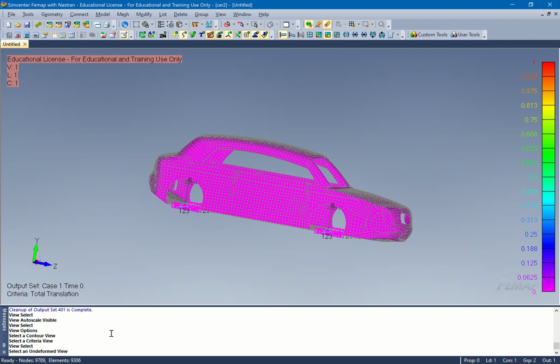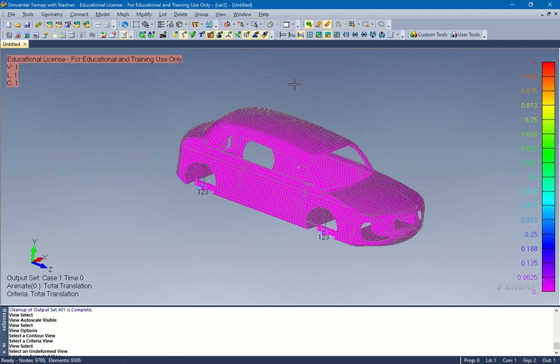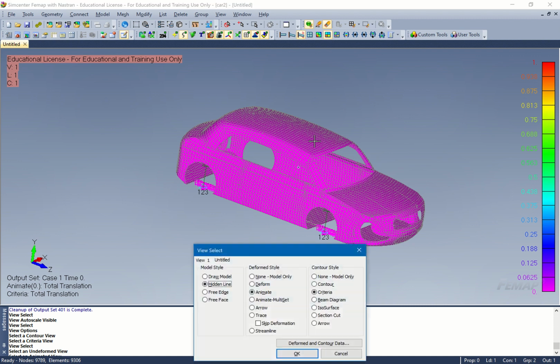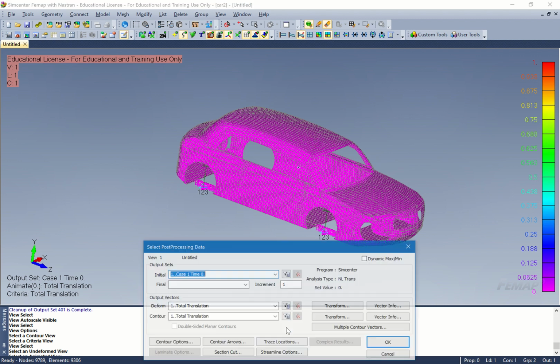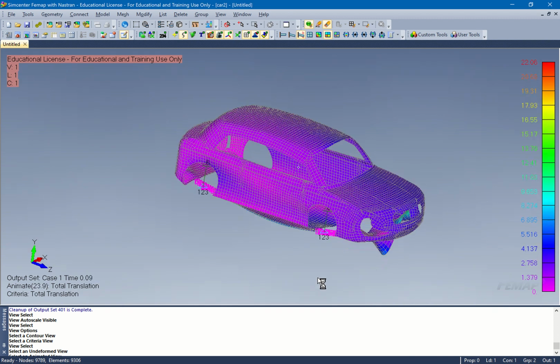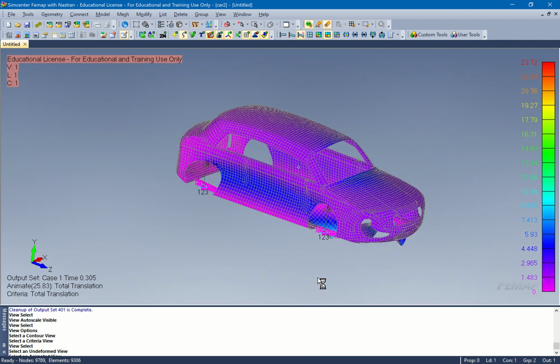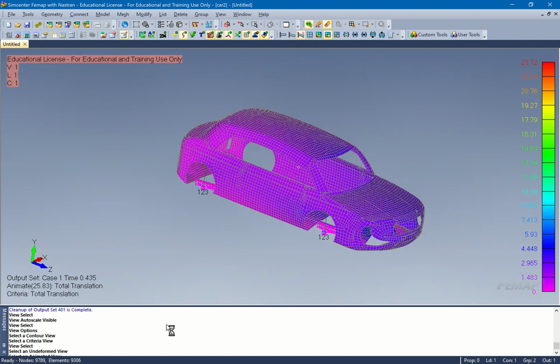Right now, you connect to the frame to this point over here, and then we're putting the force motion right there. So this is fixed 1, 2, 3, correct? So what you want to do is get rid of that constraint. Make a coincident node point right here on top of that, slightly off. And then you're going to put 3 springs in between here and here. Make this one in the X, and this the Y.